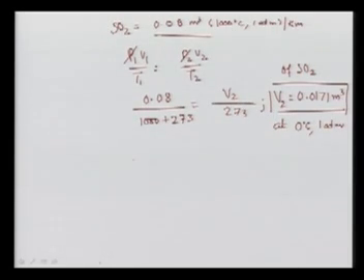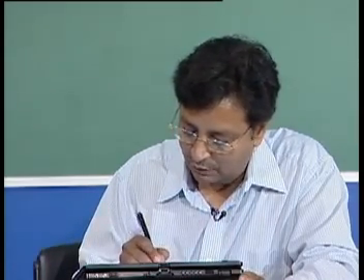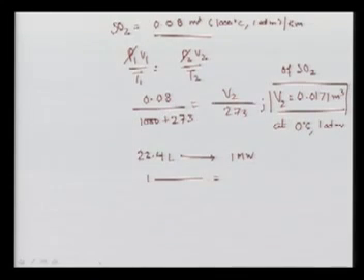If you recall from the basic Avogadro principle, 22.4 liters of gas is equal to 1 mole, or I can say 1 gram molecular weight. So, for SO2, 1 liter of SO2 will take how much mass? The SO2 molecular weight is 64, divided by 22.4 grams.